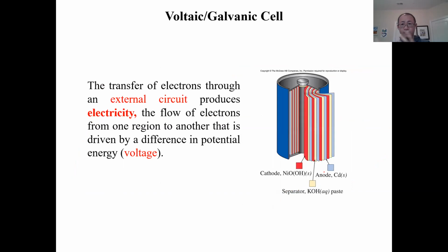So remember, in a nickel cadmium cell, the transfer of electrons is from cadmium to nickel, to realize the electron transfer that gives electricity. But because we're talking about a battery, the transfer of electrons is actually not internal. If you look at the battery, which we're going to study later as well, the cadmium and the nickel parts of the chemical substances are actually separated in a battery by some separators. So the transfer of electrons is not realized internally. The transfer of electrons is actually through the external circuit, the external wire.